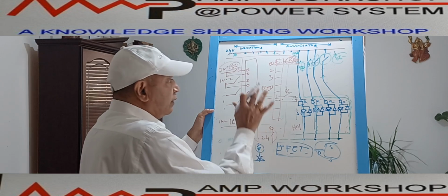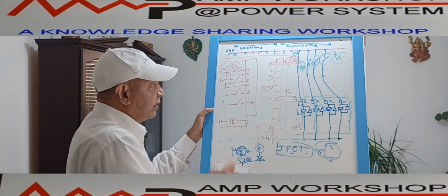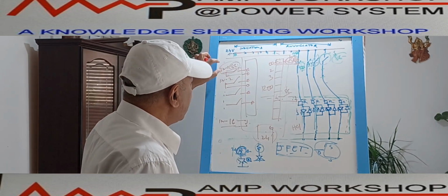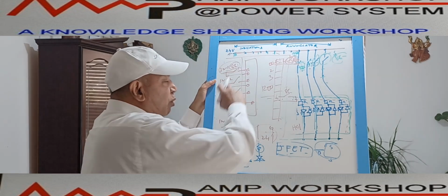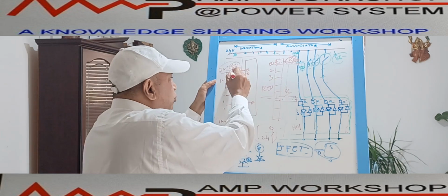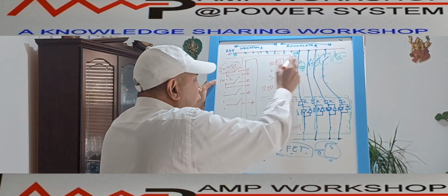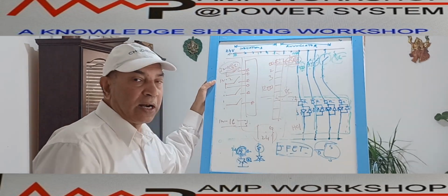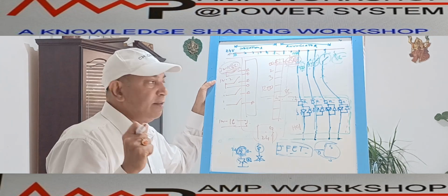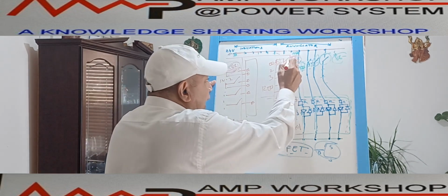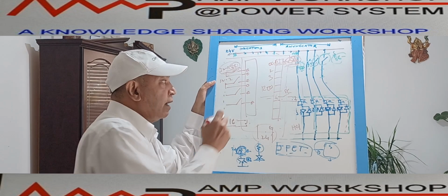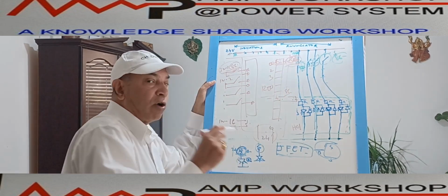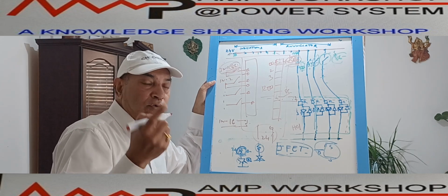One push button. Now, how does this annunciator work? The moment any of the inputs is high, the corresponding output which is programmed goes high. Suppose input 1 is 86 and I configured output 1 for 86, immediately this indication lamp will come on; in most modern annunciators it will be flashing. The moment output 1 is high, this output relay also gives one contact to the alarm, to the horn circuit.